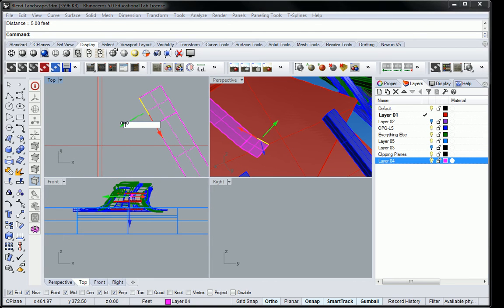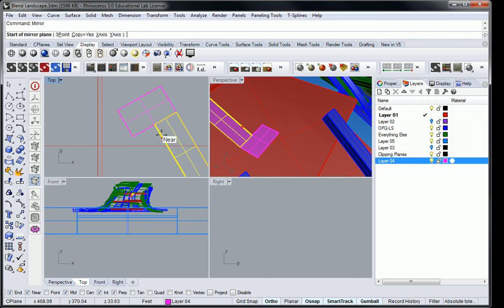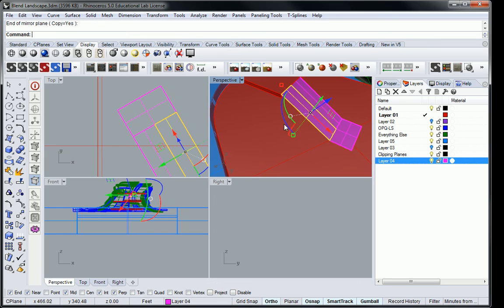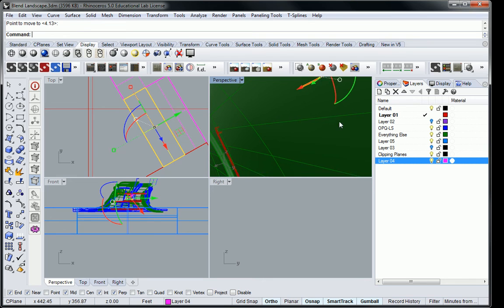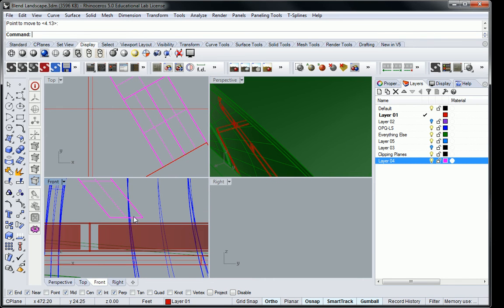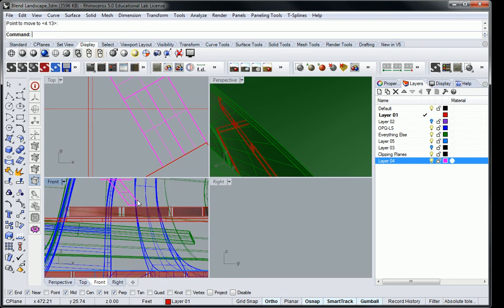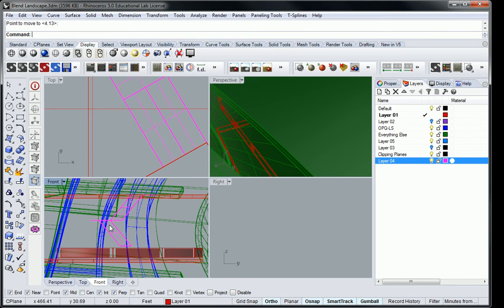I'll make this double as far, so I'm going to make this 4 feet wider. And then I can mirror this from here to here. So that makes one on the other side, right? You guys are starting to get the feel for this, right? Then I should mirror that again from here to here. Get rid of that original one, move it down. Now I've got a ramp that's going down. So what you'll need to double check here is that your ramps are making the appropriate elevation change that you needed to make. So, if you wanted to do all the pre-work, you can do that.